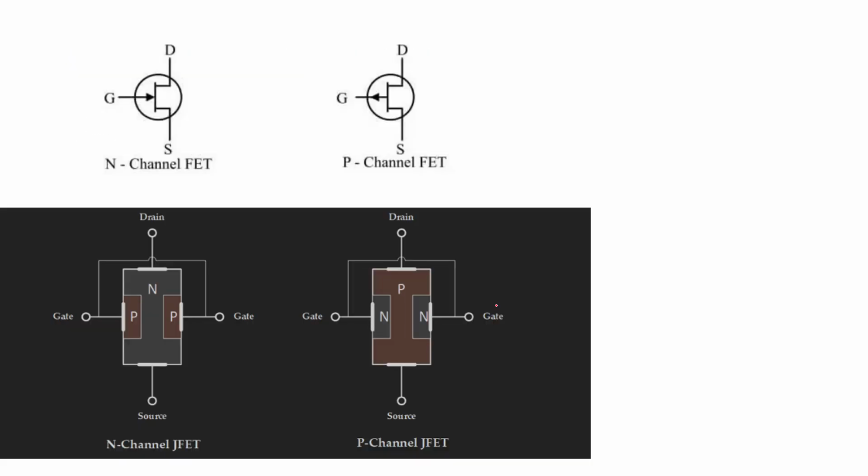So about the voltage, if we see this structure of N-channel, there is a drain terminal here. So one voltage which we connect across a drain and a source. Anyhow, these two gate terminals are internally connected, and one more voltage we connect across a gate and a source terminal. So the voltage across drain and source is considered as VDS, and one more battery is considered as VGS. In some textbooks it is VDD and VGG. Anything is fine. So drain and source voltage and gate and source voltage. How to connect it, that is how to forward bias and reverse bias, we'll discuss that.